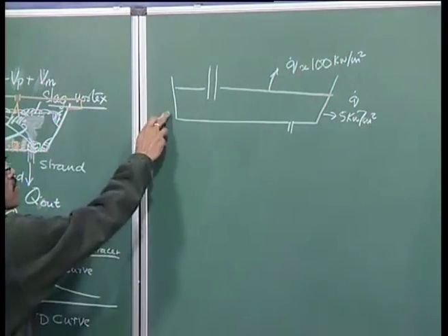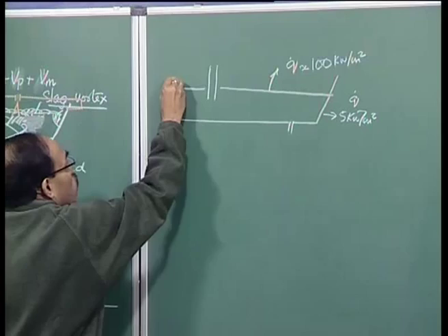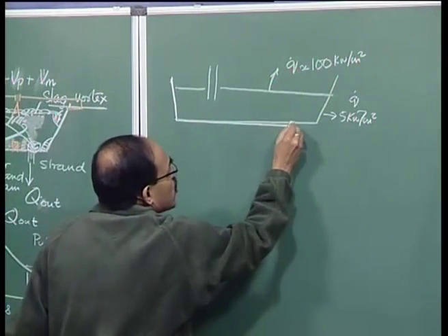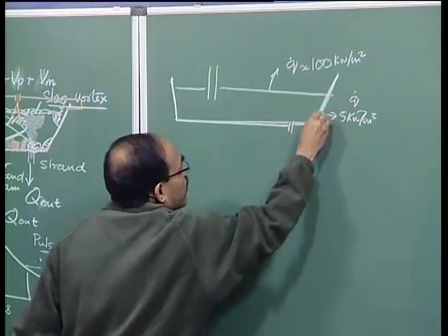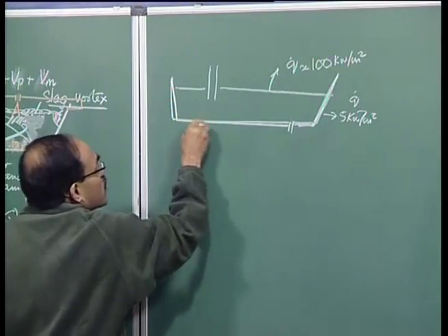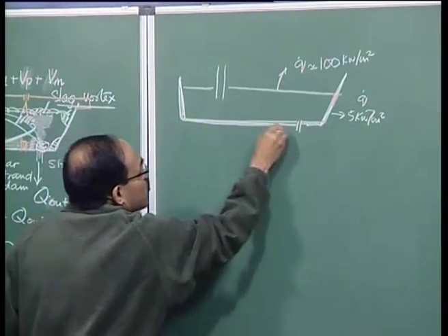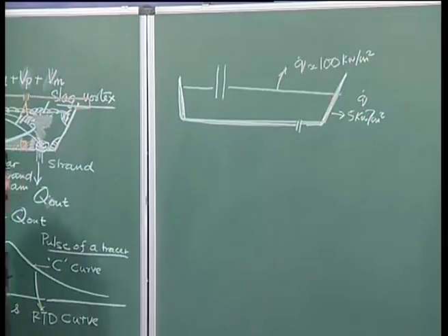So, through the walls of the tundish, smaller heat fluxes are operating, okay, and because these are refractory lined walls, therefore, the extent of heat loss is not really appreciable. Per meter square only 5 kilowatt is lost. On the other hand,